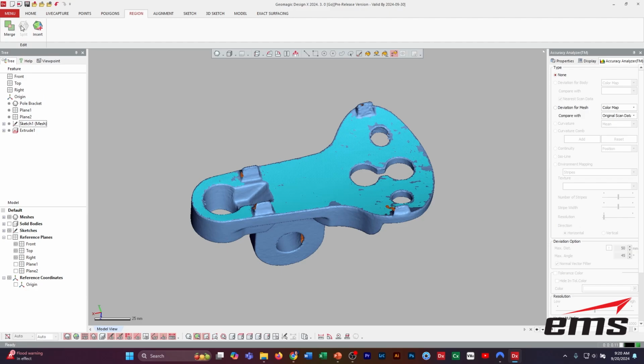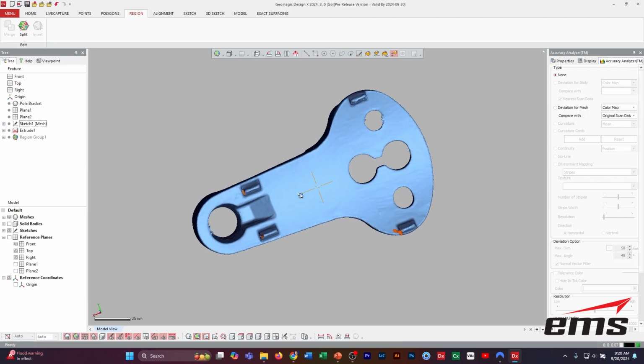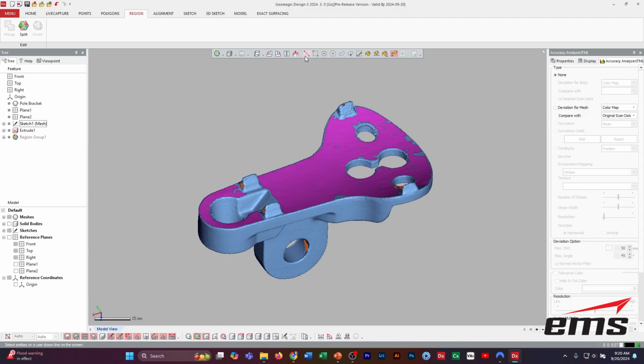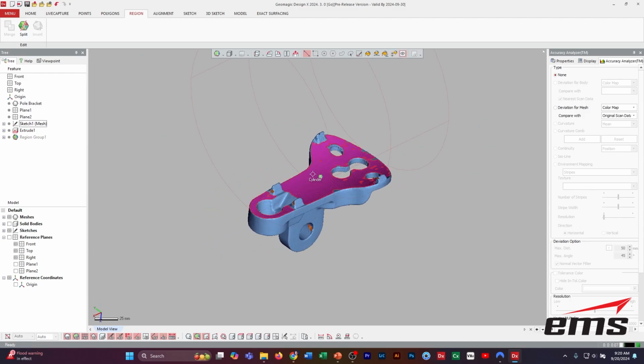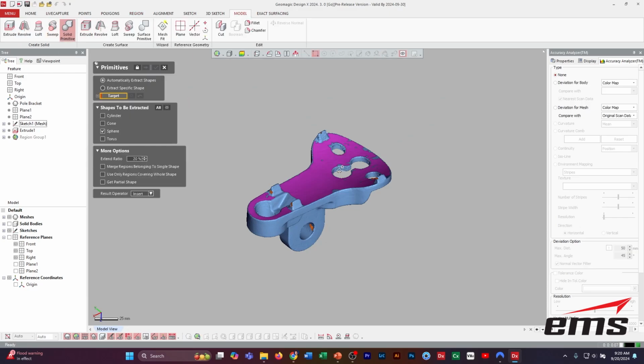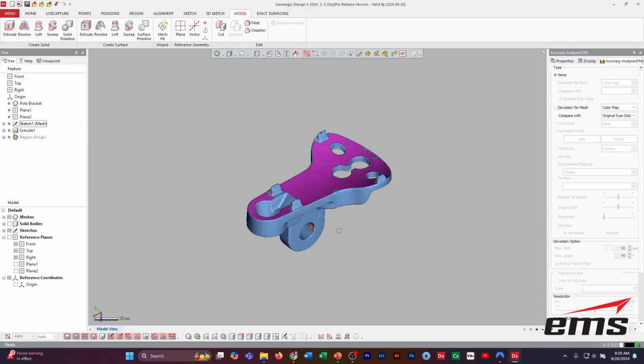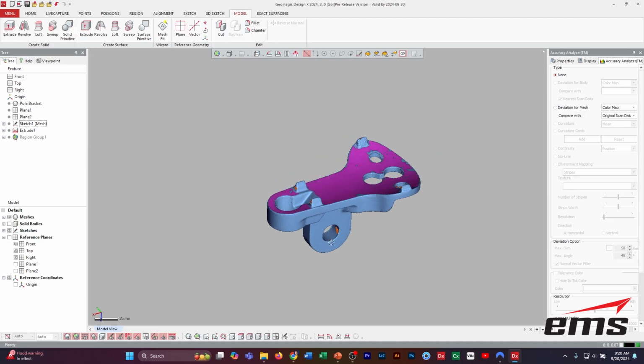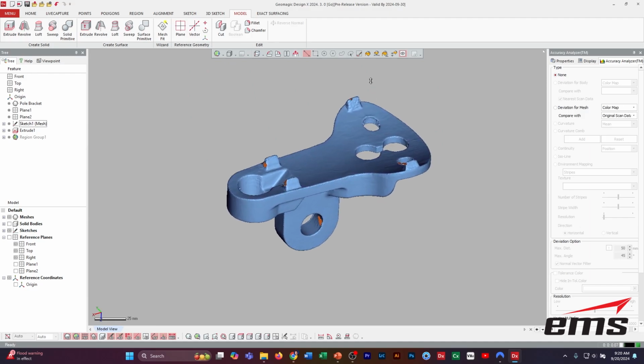Okay, so you can merge them, you can split them, or create one. Okay, what that does is that color codes the geometry. Okay, it doesn't change anything. It just now color codes it. And if you highlight over, it says, hey, this looks like a cylinder. Okay, so if I did want to create a cylinder, I could come right under here, pick this, and fit a cylinder. Okay, so not only does it highlight it, but then it tries to, let's create one more.